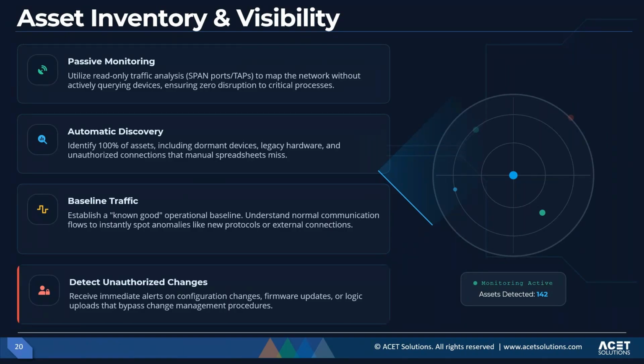RTUs, and safety controllers. By simply listening to the traffic at the SPAN port and tap, they can identify devices, protocols, firmware versions, communication patterns, and even vulnerabilities without interfering with operations. Automatic discovery capability helps build and maintain a continuously updated asset inventory.